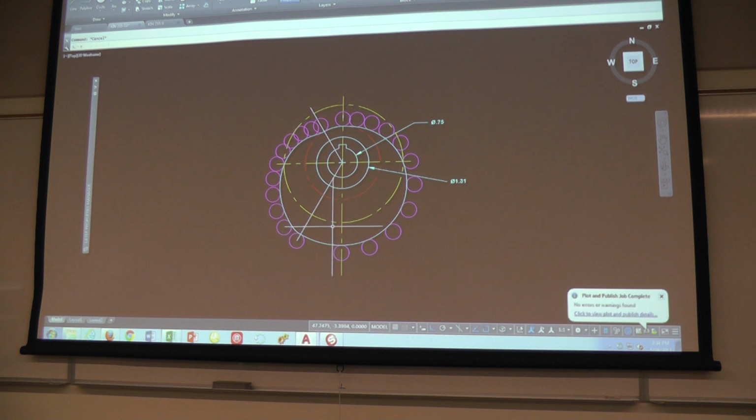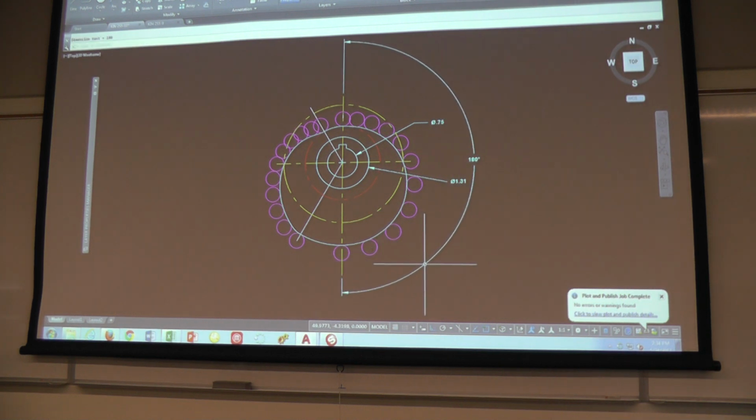Okay, well I can fool you, AutoCAD. I can do a rotate command, this one, and use the center point. Positive number, I'm just going to say 0.25. I'm going to put an angular dimension in here. It gives me 180 degrees. This one is supposed to be 30.